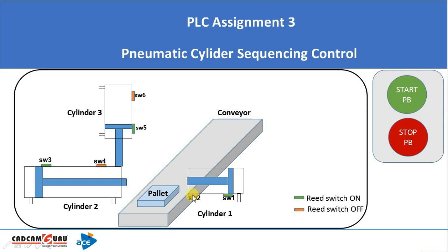After this assignment, you will be able to create a ladder logic for pneumatic cylinders or any pneumatic application, and you will be able to use a timer instruction in RS Logix Micro software. So let's see what are the conditions to operate these cylinders.